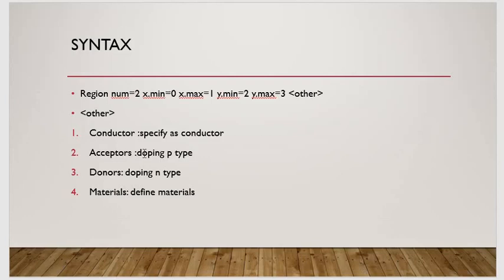And one more thing, sometimes you don't need to define using materials, because some materials are already present here. If you ignore the materials, you can just write oxide and it will take that. Oxynitride also, it will take that. You don't need to write materials separately. You just write gallium nitride, it is also present. Sapphire is also present. Amorphous silicon is also present here. So you can define all these things here.